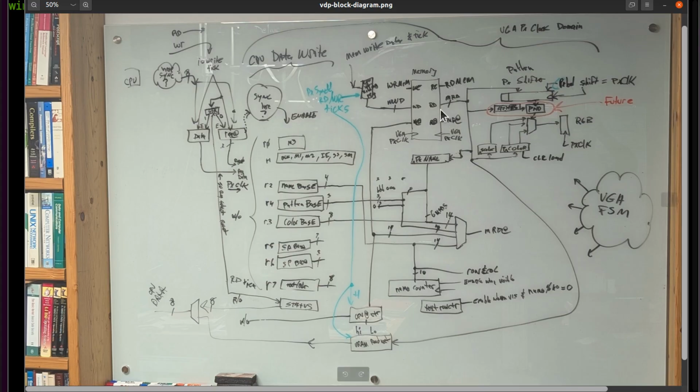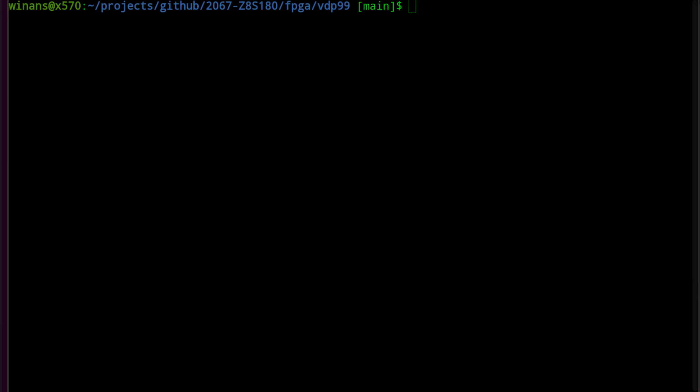But we need to build our memory. Our VRAM module has to deal with the fact that I've got two readers, one writer. I've got this clock, this counter that runs every time the CPU writes a byte or reads a byte. I need to advance to the next address down here, and you're going to have to see some sort of priority logic in my implementation as well, in two different ways that reading will take place.